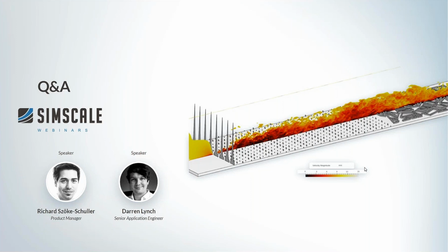We are working on a solution where we can basically strip down 3/4 of the simulation domain by not modeling the wind tunnel roughness elements explicitly, but having a solution that would already at the inlet provide us with the correct mean, but also the fluctuating parts of the flow according to the specifications of the exposure category and the inflow type that you would like to have for a specific case. And then we can save a lot of money on the simulation side as well as time.